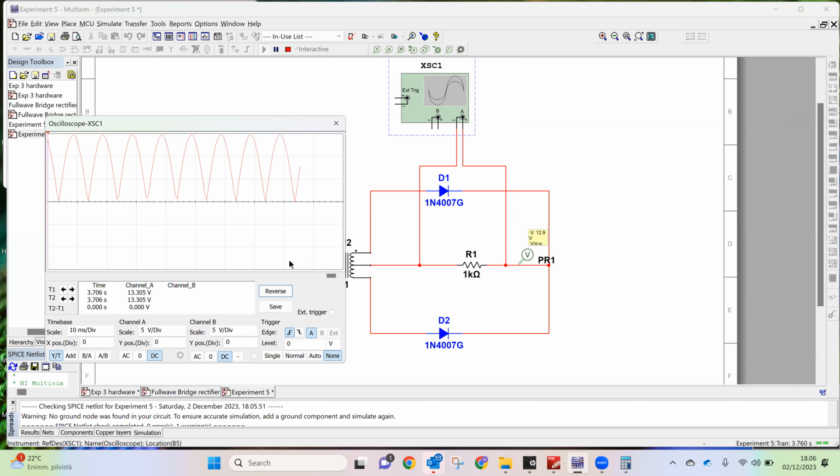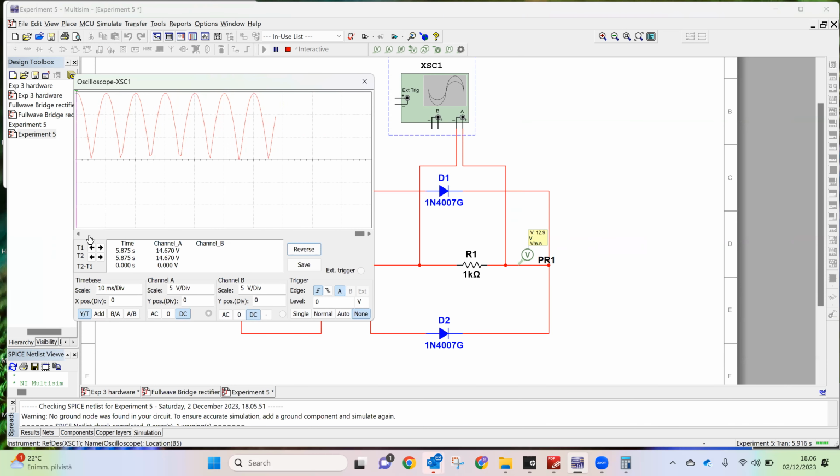The function of the capacitor is to remove the ripples. I can maybe also ask you what is the purpose of taking the capacitor, and also you will calculate the ripple amplitude like this, one cursor here and one cursor here. Now the ripple amplitude is 14.032.